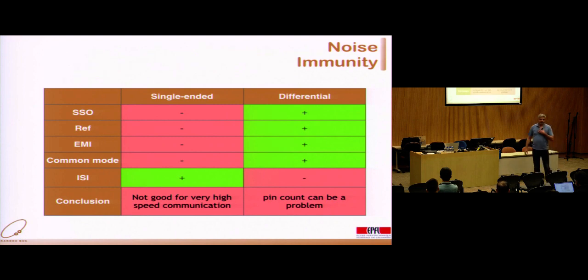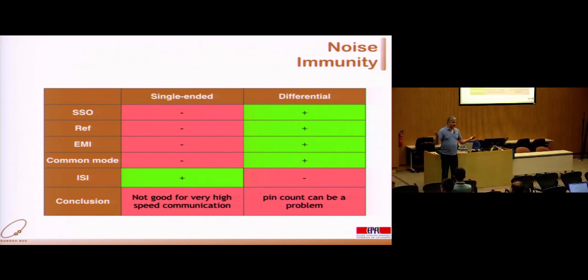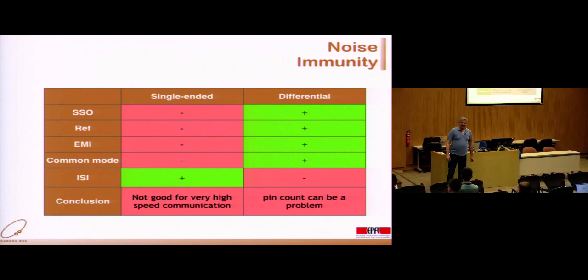So the question was, what if at the comparator you get something that's close to 0? What does the comparator give back to you? It completely depends on the implementation of that comparator. Very often, all these comparators have a blind region. If you are within that region, then the output is basically random. So the design process makes sure that you never, ever get there. That's one of the things that these engineers do. Yes, please.